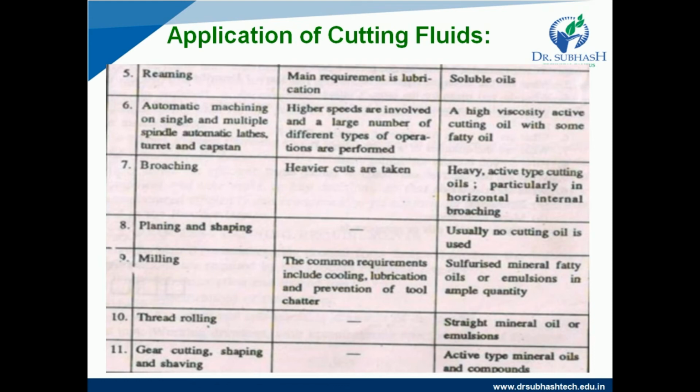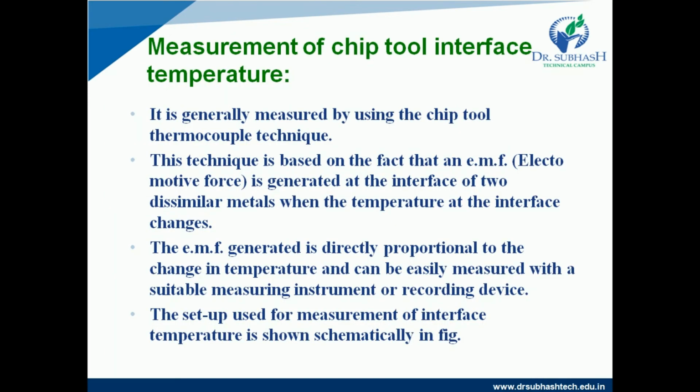So now on measurement of chip tool interface temperature. It is generally measured by the tool thermocouple technique, and this technique is based on the fact that EMF, or electromotive force, is generated at the interface of the two dissimilar metals when the temperature at the interface changes. So the three laws of thermoelectricity are applicable to the thermocouple.